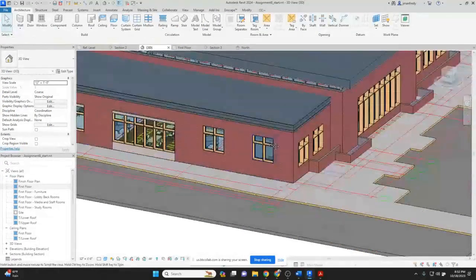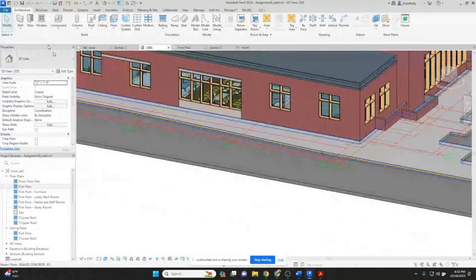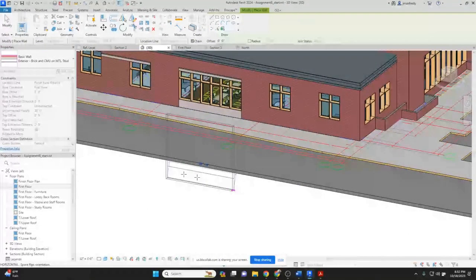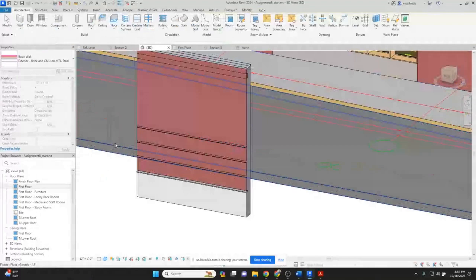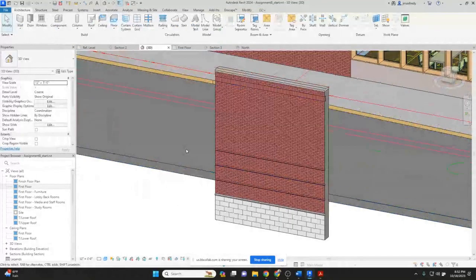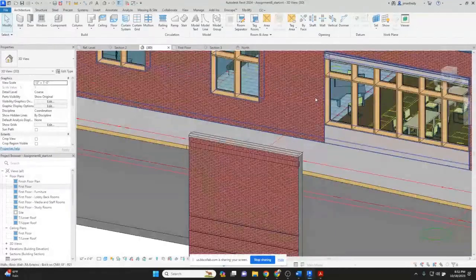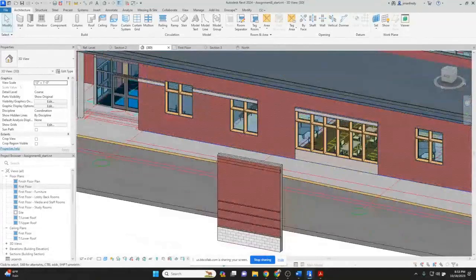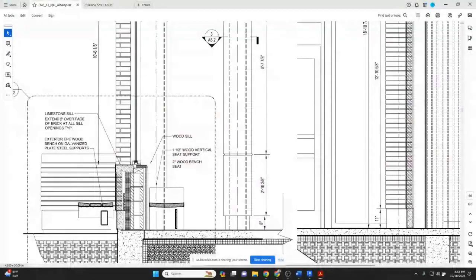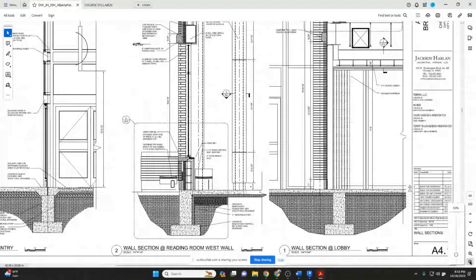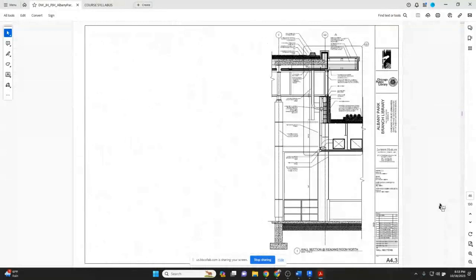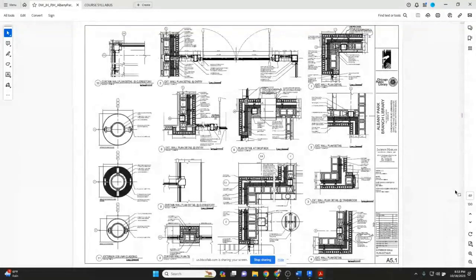You'll notice that Revit does have additional tools to do this work. If I look at this wall here, it's actually pretty intricate. So you guys are going to draw this horizontal member here. You're going to draw the lintels above, and the top of the wall should have a, I think, is there a coping up there? Let me see. No, they'll look like this. I think all the exteriors of the building are going to have the same metal coping.